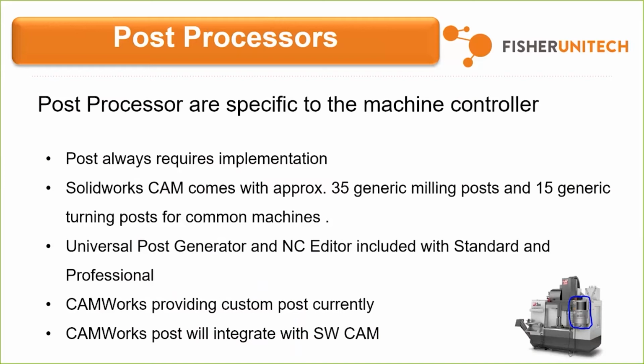SOLIDWORKS CAM comes with about 35 generic milling posts and 15 generic turning posts. We'll get to that in just a second. You can use the universal post generator and NC editor as well to help you customize your post processors, customize your G-code. CAMWorks does provide custom posts if you need them, and CAMWorks posts will integrate with SOLIDWORKS CAM.